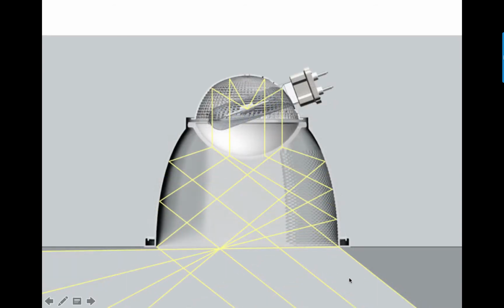And there's a million variations on these, and of course they are somewhat based in the old style light fixtures, which are based on a single light source. In this case, there's a special reflector over here called a kicker reflector. And the kicker reflector sends light right along the wall. Whereas see how here there is an angle where the light is kind of cut off. Here they're trying to wash this wall by kicking light out vertically. And again, it's just using the geometry and these funny little puckery things.